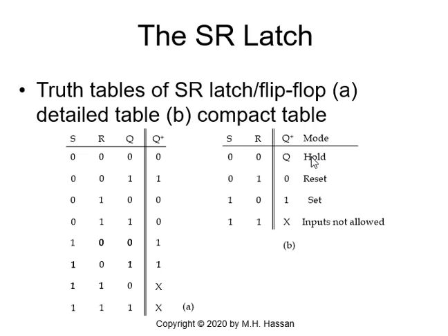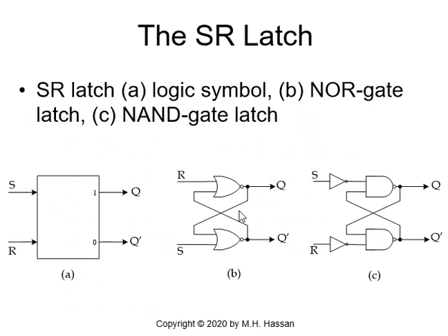Now let's go and check the next row, the third row, when we changed R to 1. Again, we will force the circuit to have a Q0 or a Q1. When Q is 0, Q prime will be equal to 1. And here we set R equal to 1 and S equal to 0. So in this case, in the upper node, since this is 0 and this is 1, the upper NOR will give me 1 NOR 0, and this will be 0.